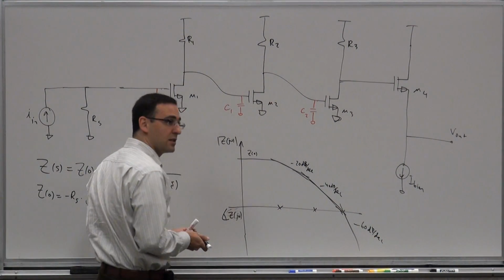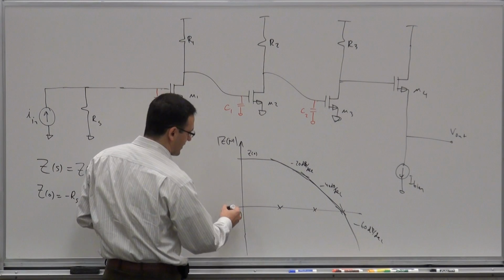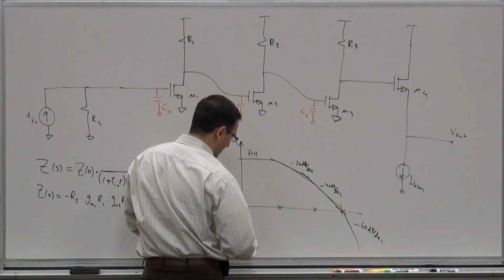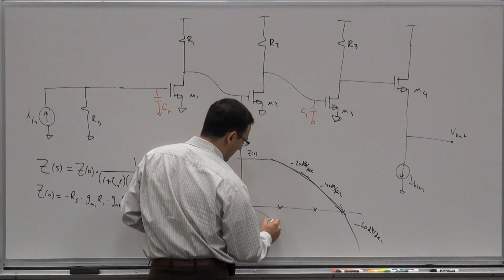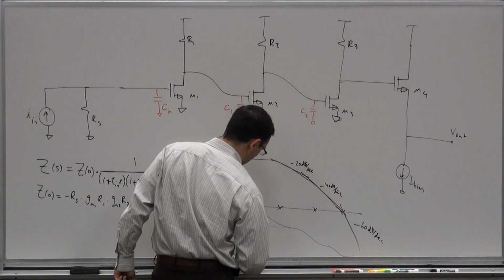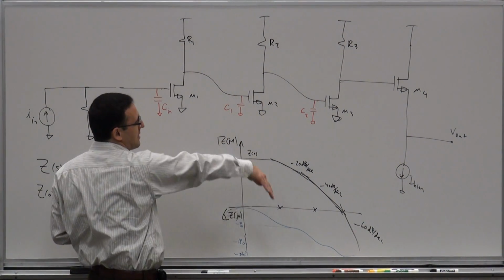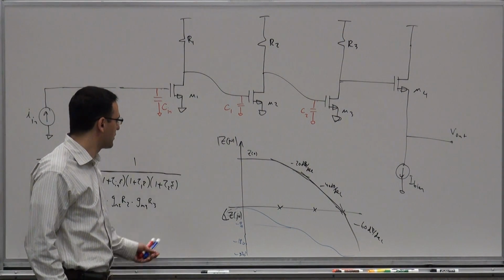And then how about the phase? These are left half plane basic poles. So basically they just constantly drop the phase. So you go through 3 steps: minus 90, minus 180, minus 270 degrees. If you look at this transfer function, it's a monotonically dropping thing.